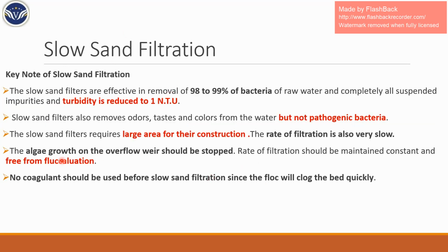Some keynotes about slow sand filter. It kills around 98 to 99% of the bacteria. It removes suspended impurities, and it reduces the turbidity to around 1 NTU.